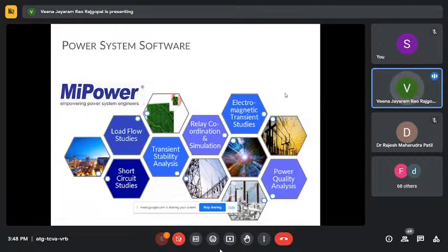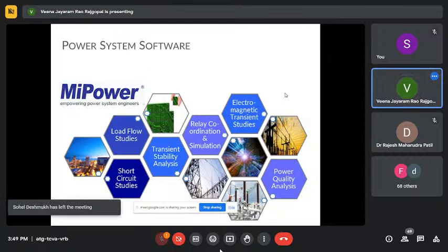There you're observing the system at different intervals of time, so you can be performing the transient studies using the software. And also when it comes to electromagnetic transients, like arcing flash or magnetizing inrush current, where you want to observe the system during the transient, we have a module for doing such kind of analysis, that is electromagnetic transient analysis. There you'll be observing the system in microseconds. So your time interval for observation will be in that. And also nanoseconds, like surge arrester studies or power surge studies.